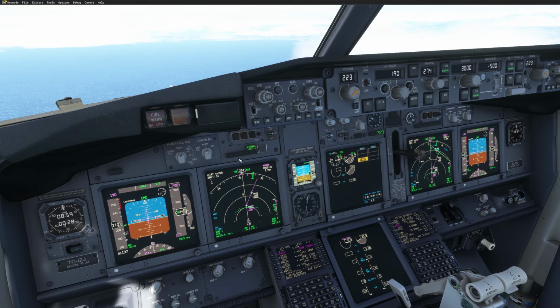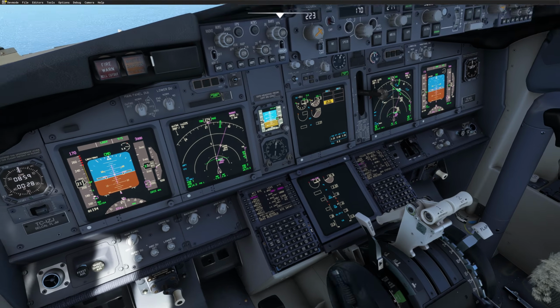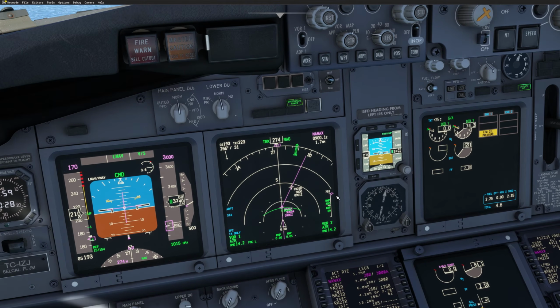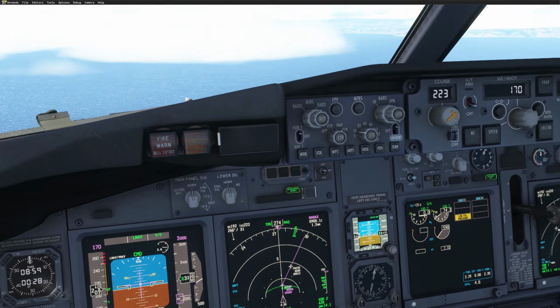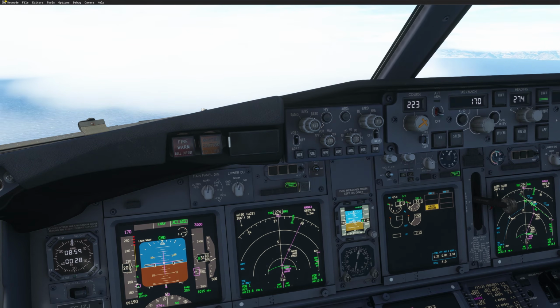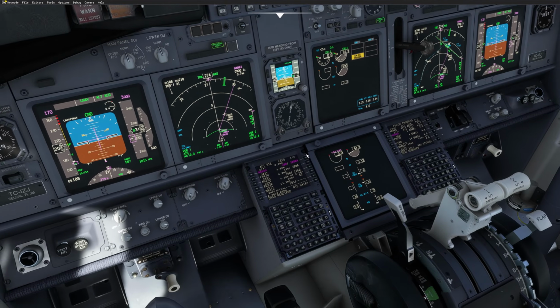Okay, cleared to land, perfect. Alright, let's go flaps 5 now. We'll bug 5. I went vertical speed for that, as I have the speed brake as well there. So the aircraft will be maintaining now 3,000 feet. You can see here our descent profile for the approach. And the minimum was 1260. We forgot to set the minimum. Alt acquired. Let's retract the speed brake.